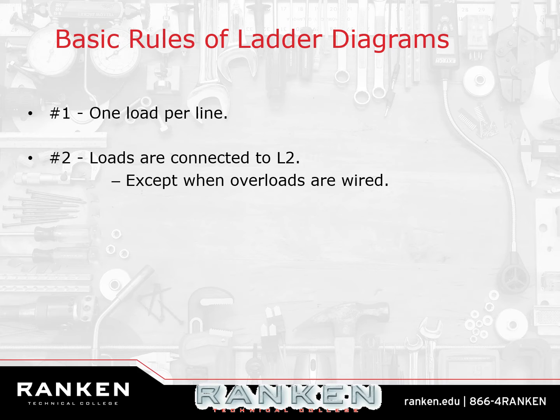So the one exception is overload contacts on a motor starter. Any other control device is never connected to L2. L2 is usually the neutral or the negative or whatever you want to call it. Okay? Everybody got that?